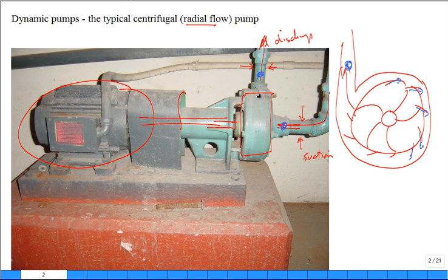That's what a pump does. Inside the pump, it imparts a lot of kinetic energy or momentum to the fluid, but that fluid is then converted in another part of the pump into a higher pressure. And the goal of the pump is to boost the pressure across the pump. You can see that this one looks like a larger suction line than the discharge, doesn't it? So a lot of times in practice they are large on the suction and small on the discharge. Okay.